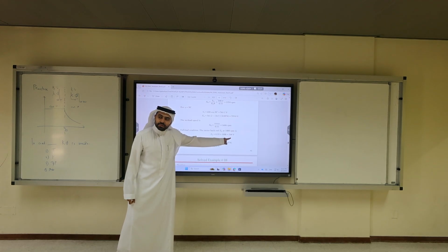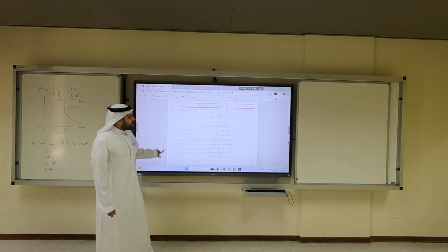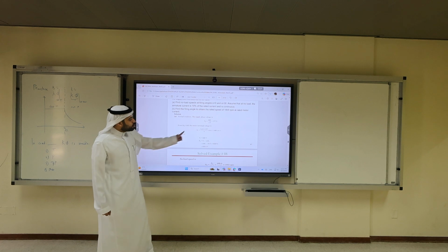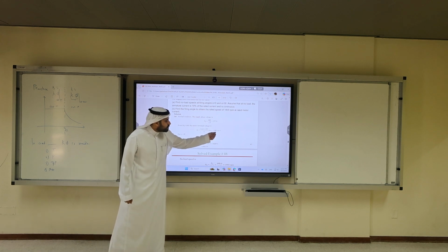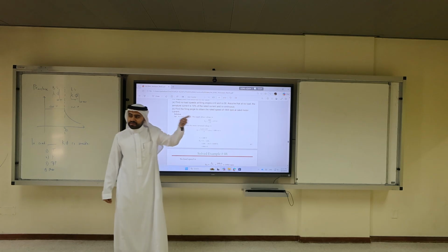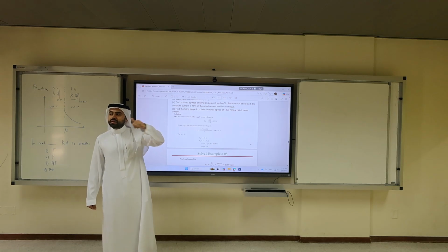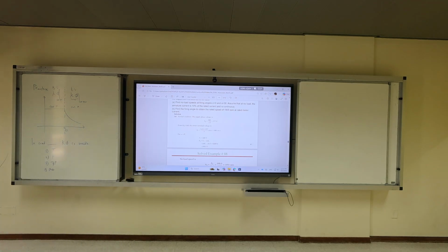That's 594. Then VT is the supply, which happens to be in this equation. So we need to find VT. What is the corresponding VT? And then we solve 648 times cosine alpha equal to that VT that we calculated. And then we can get alpha by taking cosine inverse. So this is a little bit math involved.